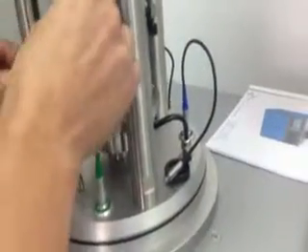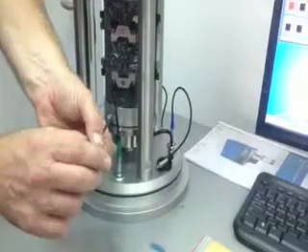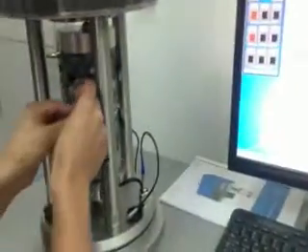Now before we put the transducers on, we'll just go back to our software. So we've had the buttons here. If I start a new test and press levels, the levels is a screen which shows the positions of the transducers. If you look at the green transducer, if I press this in, see how it's moving? Yes, I see. So when you're preparing a sample, you activate the level screen, and then by putting these on, you can see the position of the transducer.